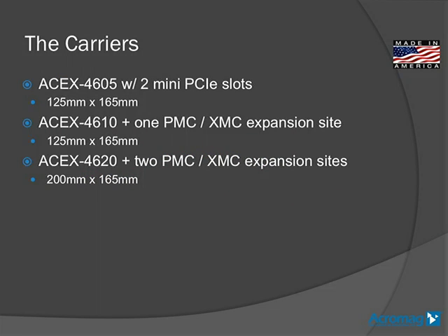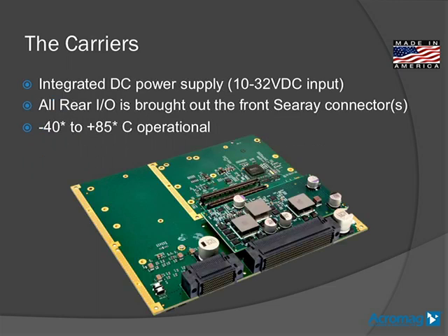The power supply section here, we're bringing in a 10 to 32 volt DC input, and we're doing all the regulation on the carrier card itself. So none of the applications using this platform will require a separate brick type power supply. If you've got, say, a 28 volt supply in a flight application, if it's clean power, bring it straight into the board. If it's not clean power, like I said, we have a power supply filter to offer for that.